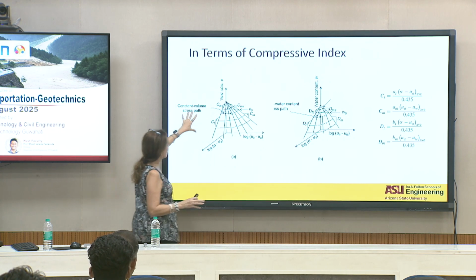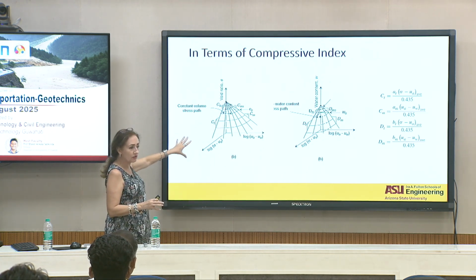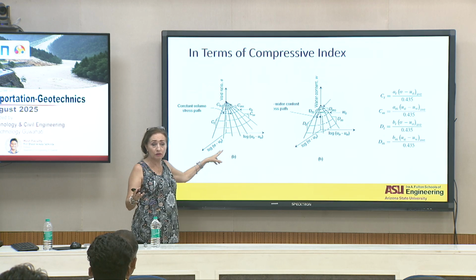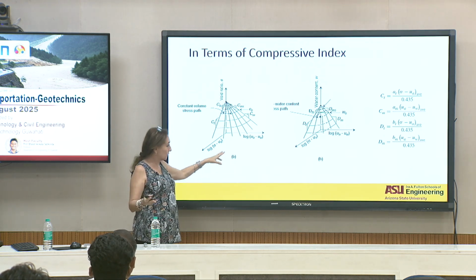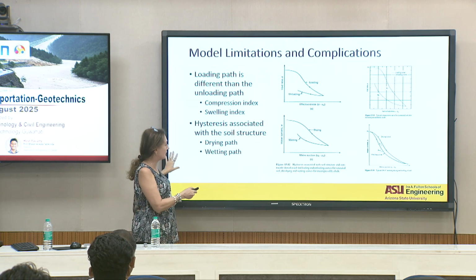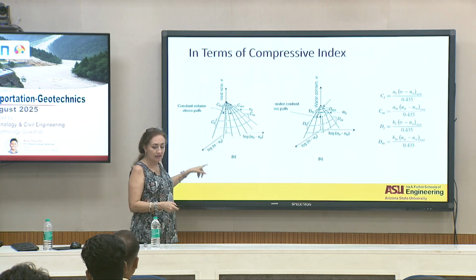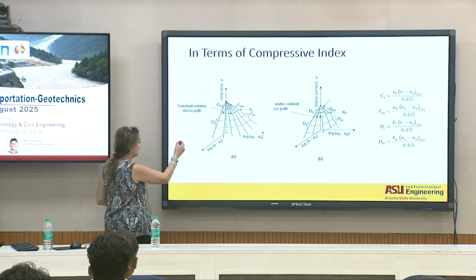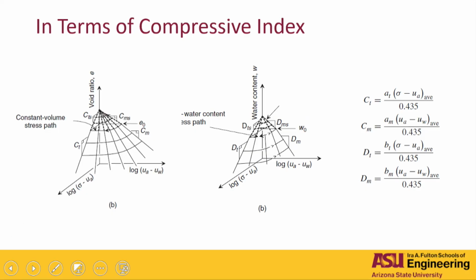Okay, now for this constitutive surface, when the soil is saturated, the pore pressure is equal to your air pressure, right? So this one is like your effective stress, right? That's your effective stress. That's the consolidation curve that you've always seen, right? So what you've got in here is this guy, right? And when the suction is zero, this one becomes your C sub C, right?